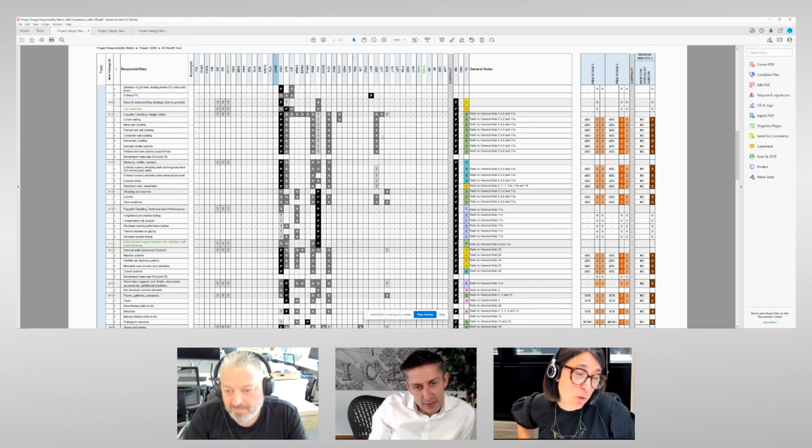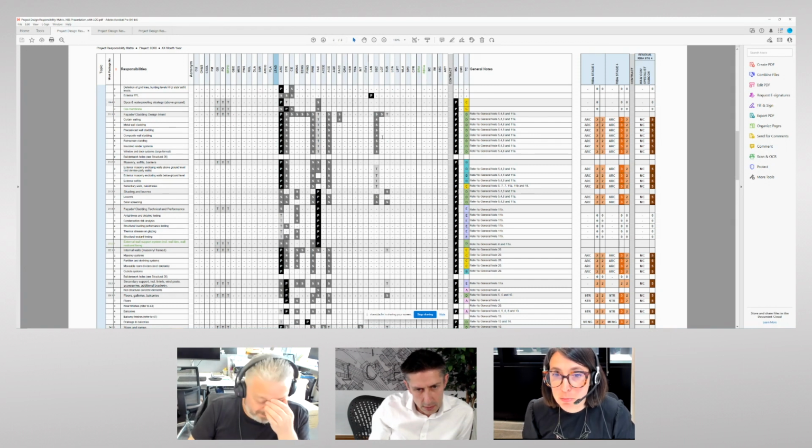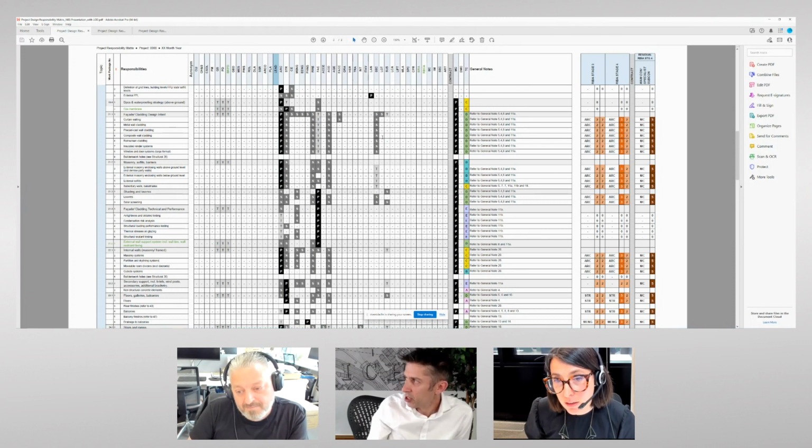Typically, things like waterproofing, below ground waterproofing, will require some level of negotiation between ourselves and the structural engineer. That will depend on foundation type, whether there's a basement, all sorts of factors. It's not an exact science. It requires negotiation and openness with the design team at the beginning of the project.